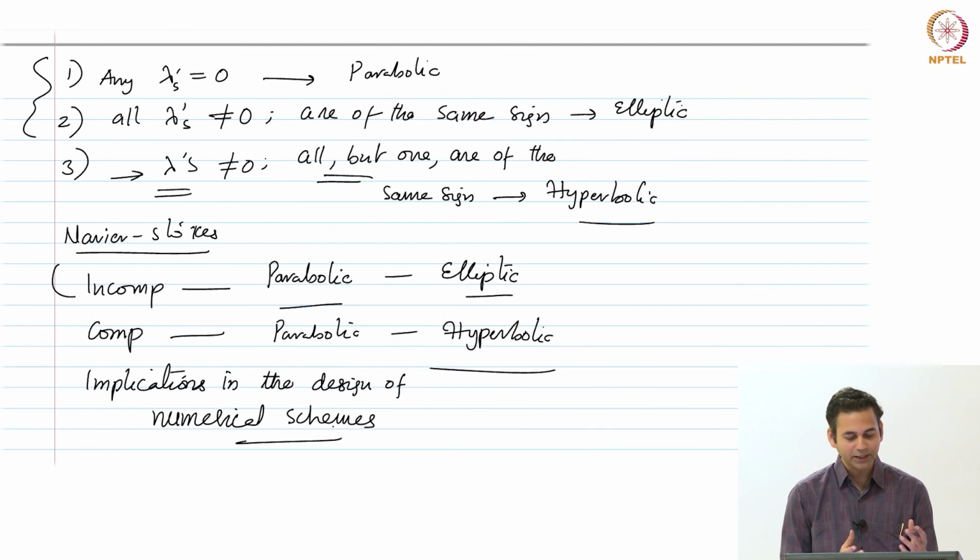Sorry? So essentially the nature of the equations would change. As a result, the things you are trying to solve would degenerate, and you would end up with stiff equations, okay. So the same problems that you would encounter in directly working with incompressible flow equations is what you would encounter if you try to solve from a compressible perspective as well, okay. So in the limit of, let's say if you have a compressible solver, you try to run it at a much lower speeds. Let's say for example Mach numbers less than 0.3 and 0.2, then you would encounter the same kind of problems as you would encounter if you start off from an incompressible flow equations, okay, for which we have some remedies, okay.